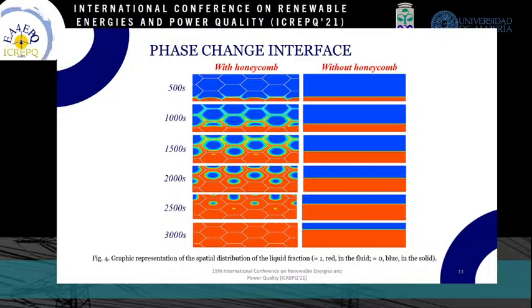We also note that the evolution of fusion begins with the edges of the core of a honeycomb and propagates towards the middle of the hexagon. After 3000 seconds, all of the PCM was melted, giving a melting fraction of close to 100% for the first configuration, with metal matrix. However, the fraction was still not completed in the second case.